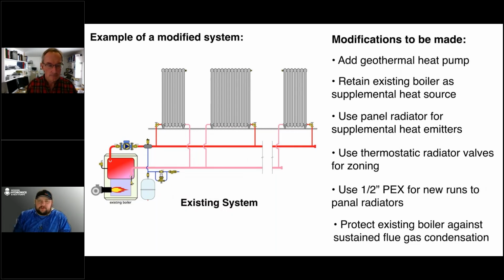We did have one other question asking about defrost cycle and the air to water heat pump. Defrost cycles are just a necessary evil. On our particular unit, where you're going to do the most defrosting is really from 45 degrees down to low 30s, just above there. The colder it gets, there's not a lot of humidity in the air to really plug up the coil. So that's really, just above freezing is where you're going to see a lot of that happen.